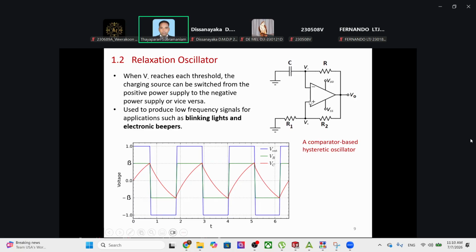If you want to go for an extension, how can you switch the power? You can check the amplifier current, how much current it needs, and then you can put a transistor, a MOSFET, in series. Either one side is sufficient, probably the VDD side.